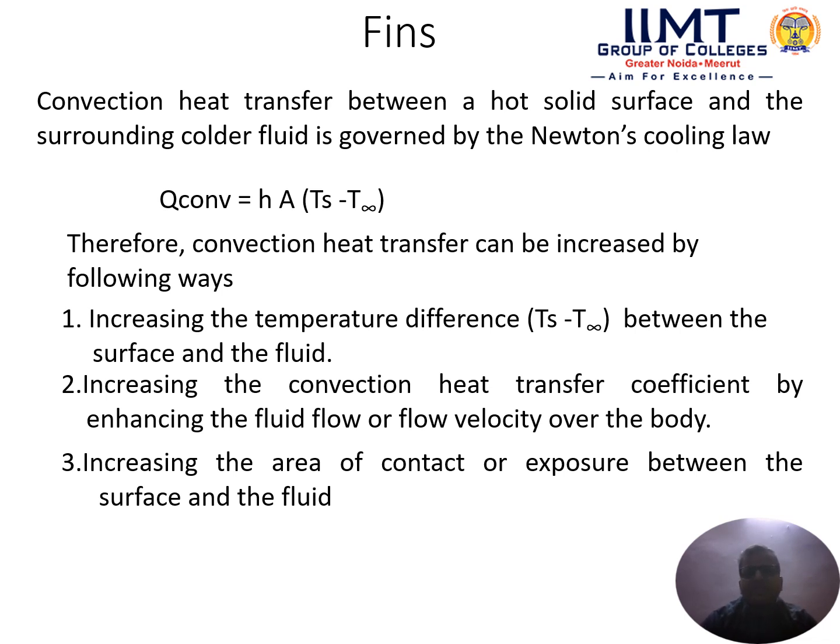But for some cases it is very difficult. For some cases, we cannot change the value of h and delta T because these are fixed by the surrounding condition. Ts is the surface temperature, and T infinity is the surrounding temperature. This will be fixed by the surrounding condition. h depends upon the surrounding atmosphere.